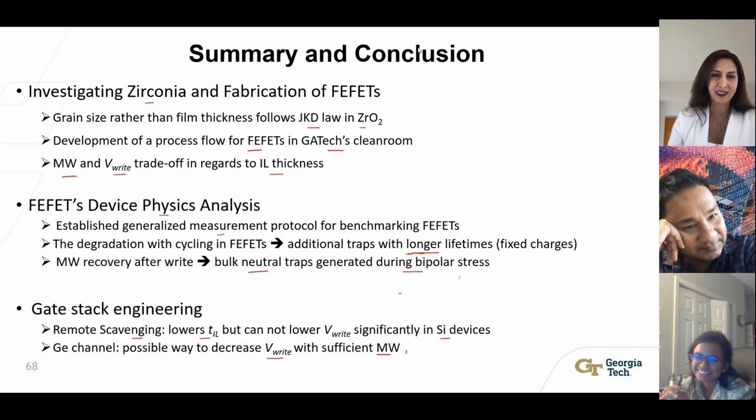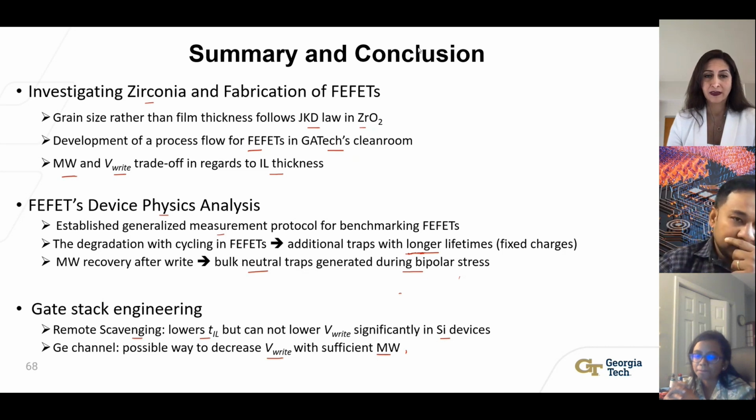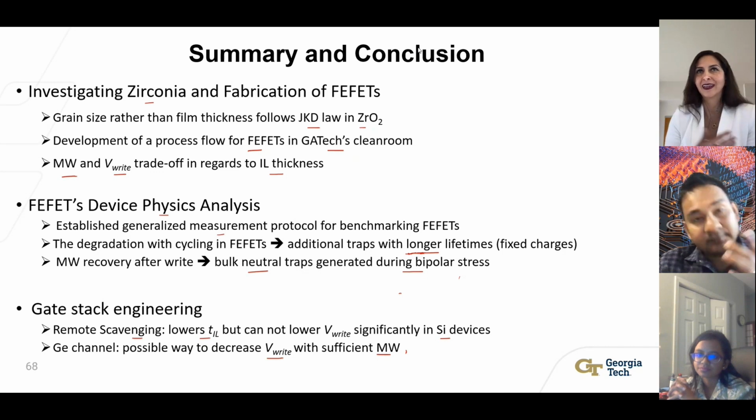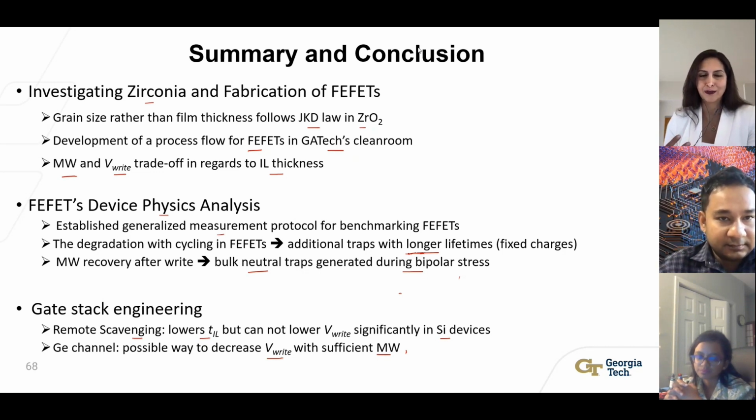given that you do have that first part that is a lot more material centered, it would be nice to have a touch more of that materials consideration. There is a lot of interface you talk about, how the interface affects it. So it's not simply about something that we decrease the thickness, this happens. Why does decreasing the thickness make this happen? Is it because you're overall changing the defects? How many defect sites do you have if you're reducing the thickness by half? Does that matter? Or is it the quality of that interfacial layer that is affected because you have made it thinner, and ALD has differential concentration of defects depending on the thickness?